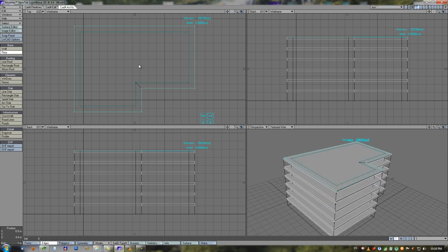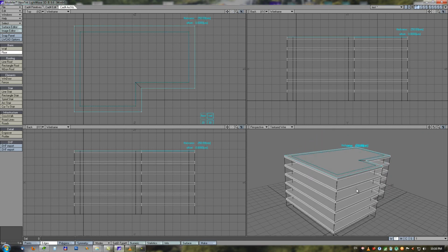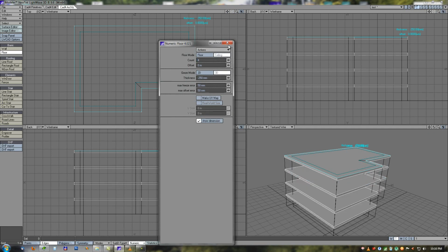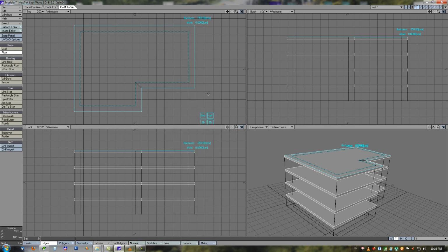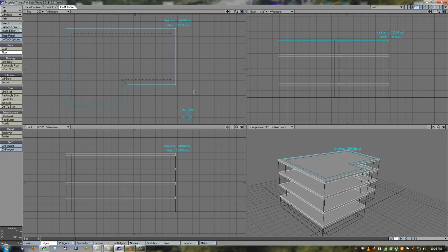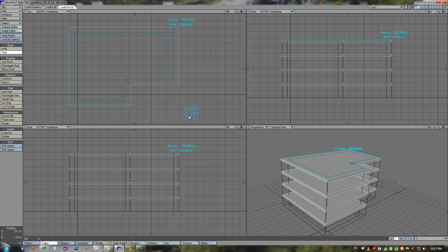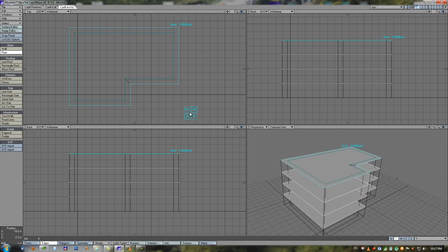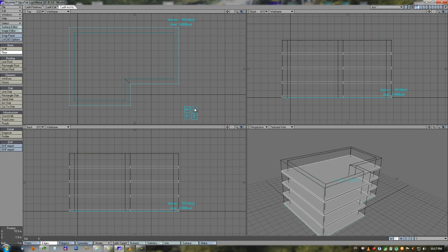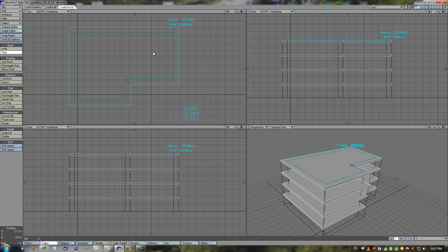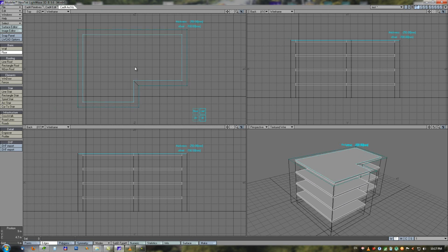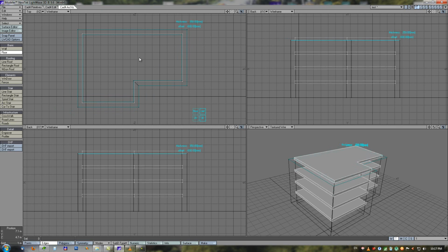Floor tool has now multiple levels options, so we can change number of floors. Some options are moved into scene. We can switch them with these OpenGL buttons. There is also new 2D mode, so there is only flat floors, polygons. We can switch between floor and sail mode, and as previously, we can also adjust the offset and thickness of the floor.